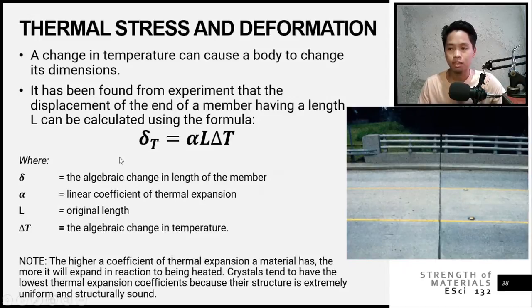Since it is steel, the temperature may affect the length of your tape. If the temperature is too high, the tape will be elongated, so if you measured 5 meters, the true length would be less than 5 meters because your steel elongated, so you must apply a correction.